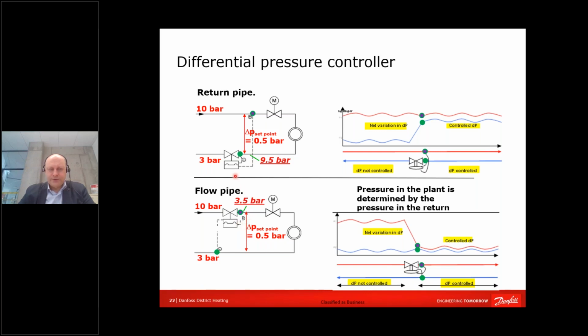And as you can see, there are normally two impulse tubes. One is marked with a plus mark, another with minus, plus higher, minus smaller. You shouldn't disconnect these pressure lines during pressure tests, so controllers should be subjected to more or less the same pressure during the pressure test. Otherwise, you may destroy the controller.